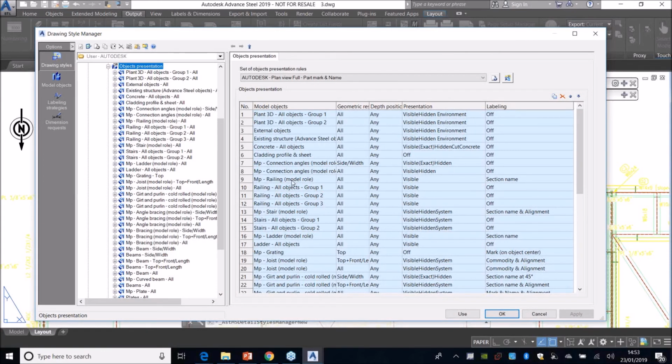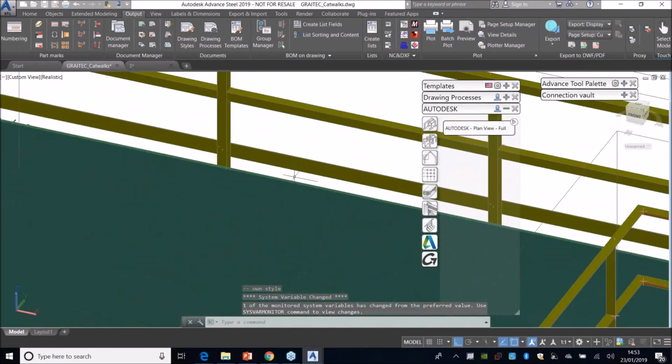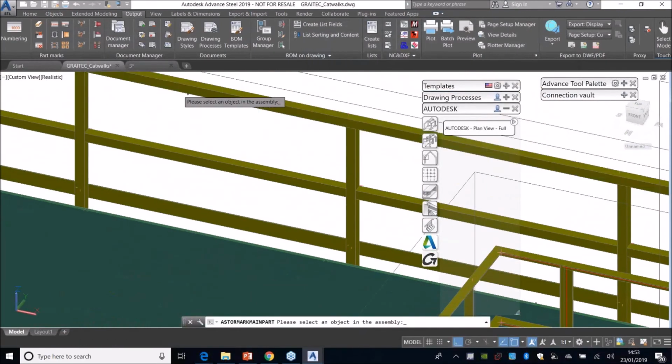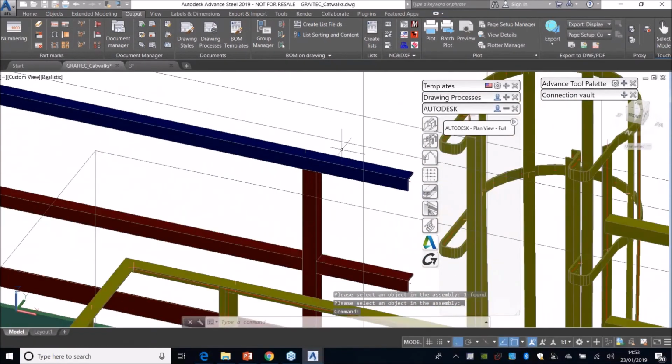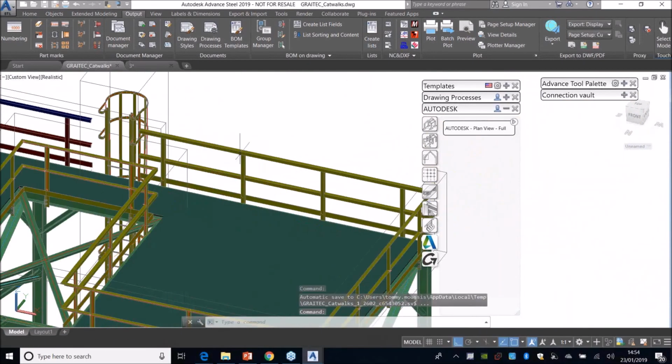We just know that there are 4 actually. So here we have the main part. The main part is typically the grab rail. And this is where you have to go and investigate the model, because on some occasions it could be the kick plate that is the main part of the assembly. So kick plate, I'm not sure if that gets utilized in the UK as a name, but when I'm talking about kick plate, I'm talking about this down here. This flat bar. It could be kick rail, sure. But this is where you have to do some investigation on occasion. You might want to see what the main part is, if it's a kick rail or kick plate, or if it's the top rail system.